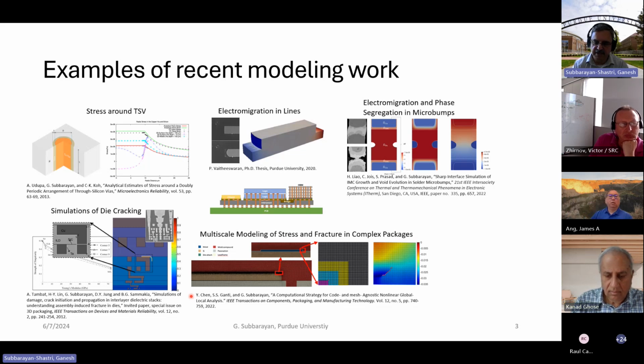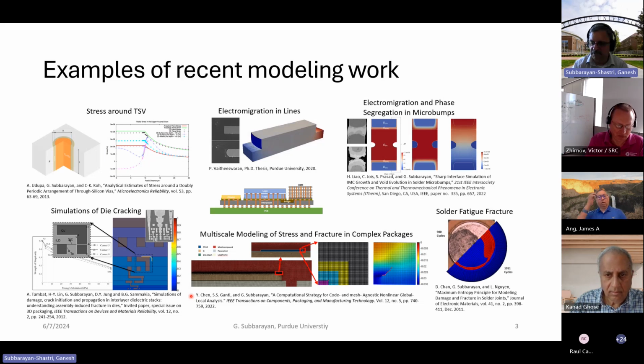Generally, finite element models are very poorly suited for these kinds of length scale bridging because the mesh needs to span the entire length scale. That makes it challenging. So we developed alternative techniques where you can mix and match meshes of different sizes and even computational tools, different commercial tools. And then finally, some reliability models where we've developed first principles models for predicting life accurately.